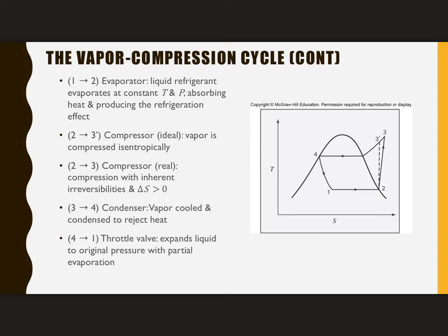And now then I want to reverse my pump. Now the reverse of a pump is for a liquid, and really the equipment that would be the reverse of that is a turbine. But a liquid turbine simply is a lot of work for very little effort. It's not cost effective, it's a maintenance nightmare. And so instead of trying to recapture some of the work by using a liquid turbine, instead people just use a throttling valve. A throttling valve is essentially a torture device for liquids.